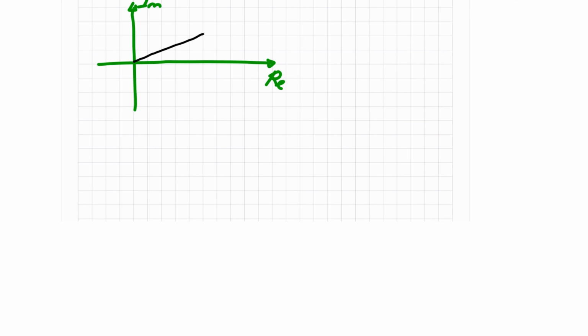Now this is still our voltage here. That's our Vm. This is our phase angle theta V. Theta I this time is 90 degrees off and in lead. So we have I is right here, and this 90 degrees. So this is Im, and this phase here is theta I.